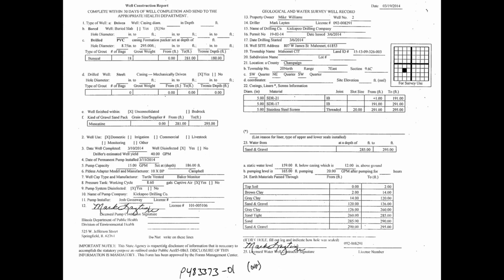And most of the time what a driller will do is put in a pump to test pump like this that's twice or at least more than the pump that they're going to actually install for the home. And so a lot of times we see they used a 25 gallon per minute pump, and then over here on the left side, in this case, they put in a 15 gallon per minute pump, and they set it at 186. No reason to go down any further. The closer you get to the screen, the more likely to cause turbulence and stir up material, solids. And so you keep the pump as high as you can, but well into the water, so you never have to worry about drawdown getting to the well.